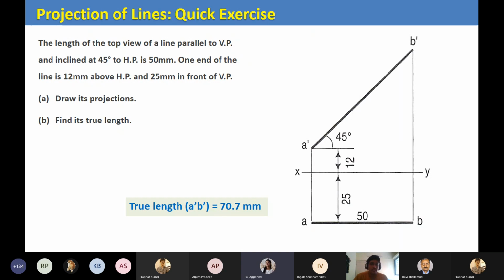Can you explain the case where you don't rotate the scale exactly to 90 degrees but keep it at some angle? How is the projection angle then? Yes, that is also the thing. Here this is the angle the line makes with the horizontal plane. When you go to some other position, you see a different angle, but I am keeping this angle constant with respect to HP, the horizontal plane. You see a much bigger angle here. That means in the projection you see a different angle, but in actual this angle is the same.